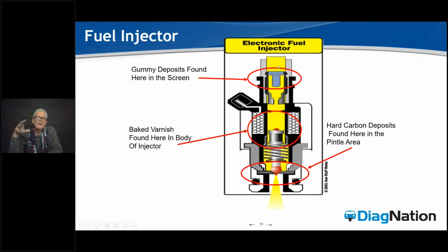I've had several of these vehicles apart, and if you take these injectors out, in a lot of these cases, once they're badly fouled, and you just take a white rag or even a white piece of paper if you don't have a white rag, and you flip those injectors upside down and just knock them on the bench, you will be shocked at what comes out of them, at what it looks like. Some of them look like pink salts. Some of them look like rusty little flakes of rust. Some of them look like white salts. I've seen some white salt looking stuff on Hondas. Okay, guys, there are problems with this.